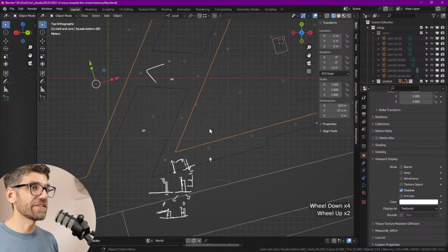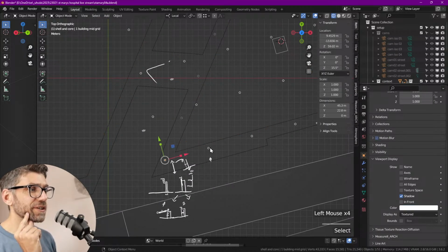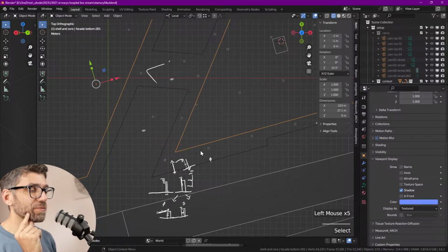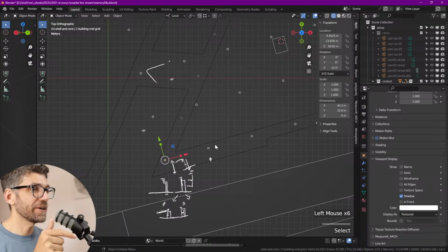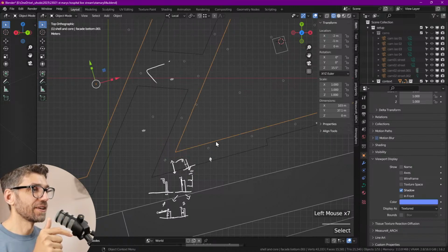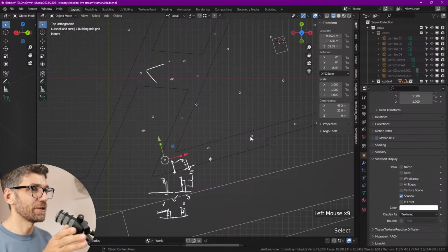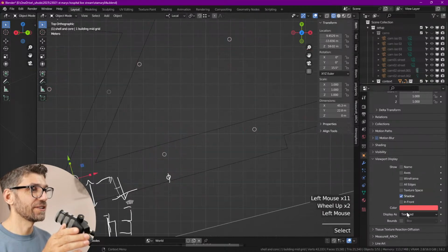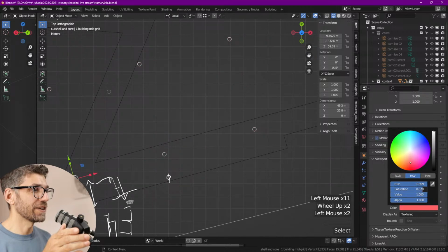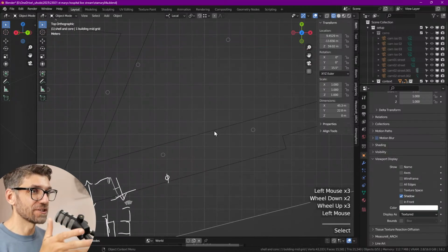And in here we can give a specific color, which, let's see, does it work? How did that color work for this? This is a color, but this is not a color. Okay, so I think we can only give it to meshes. Curves, because this is a curve, it doesn't pick up that color, but a mesh does. So if I change the color of this, does it change? Yes, it does. Strange. Anyways, so now you've learned it: we can only give colors to meshes, and these are curve objects.